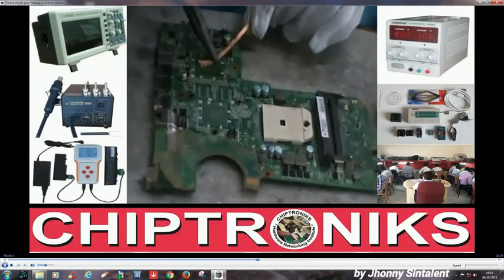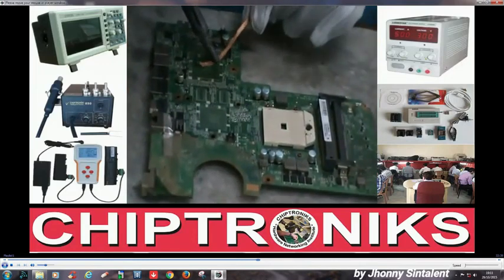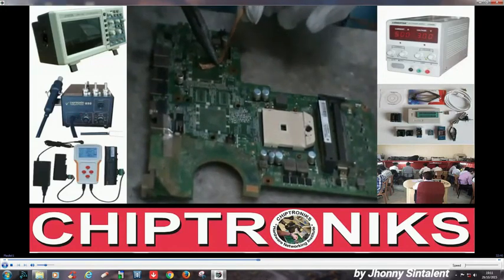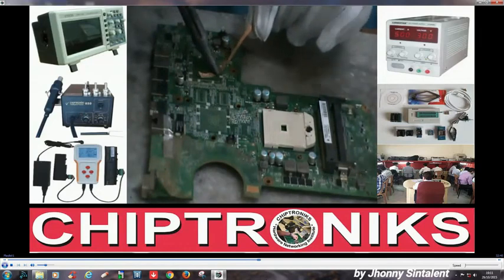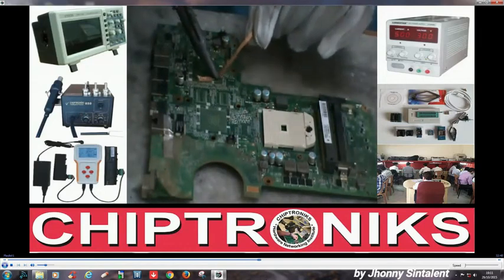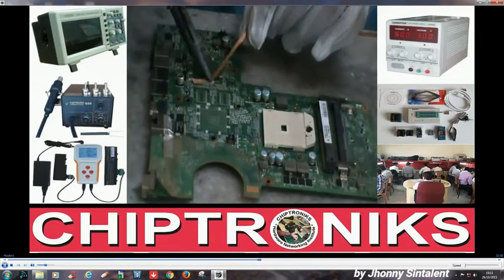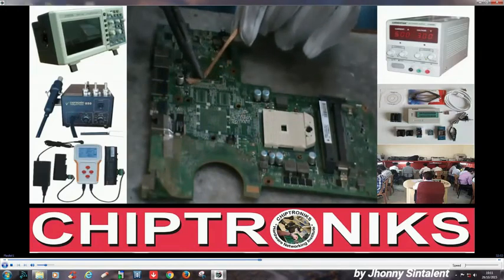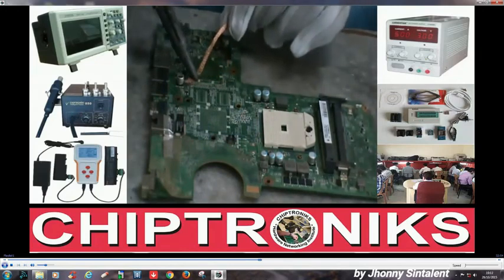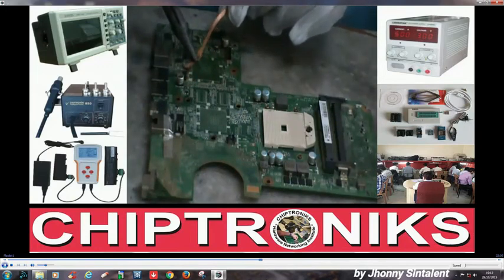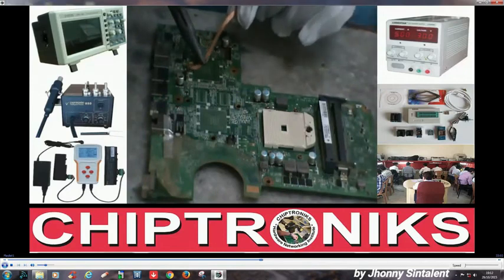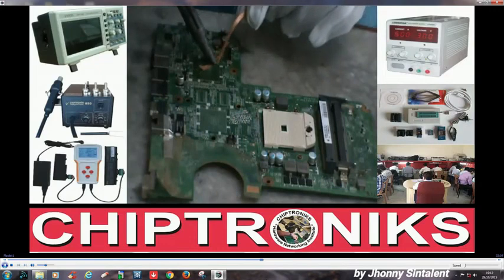And for board cleaning, we can use a very good quality, branded solder iron, and you can also use some edge type solder bits, but we are using a normal one. That is also good. But what is important is a very good quality solder iron, preferably 50 to 60 watt, and a very good quality desoldering wire, because that is very important.